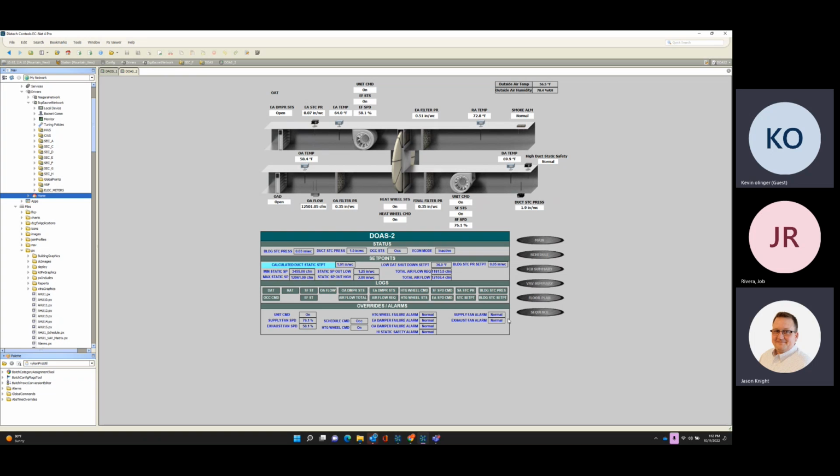But if you just see it down here by itself, this is just logic that I wrote that says, hey, the fan is commanded on, does the status match? And there's nothing to reset with that. That's just letting the operator know that you're in that condition, and then you'll have to physically correct that condition and then that alarm goes away.